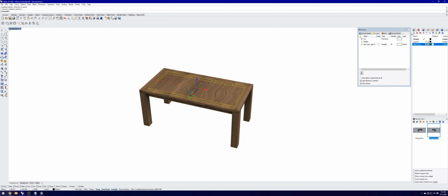But within Rhino, if you want to apply a material to your geometry, you're just going to click on this little materials tab, and you can create a new material by clicking the plus button. I typically start by pressing custom. You can name it whatever you want. I'm just going to leave mine custom for now because I already have my material in here.